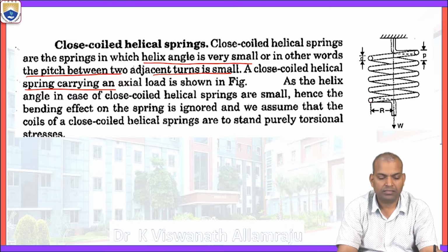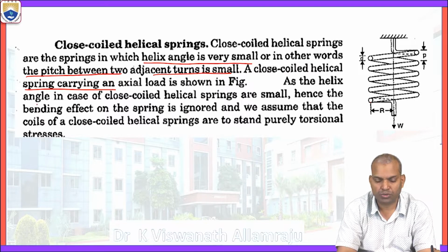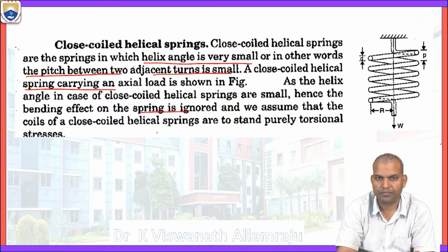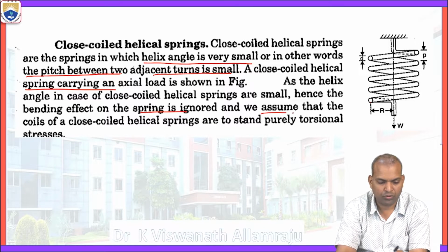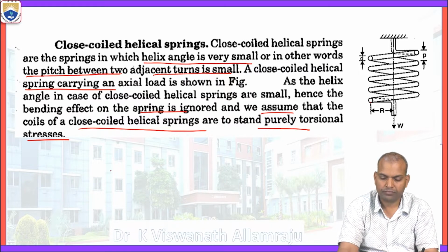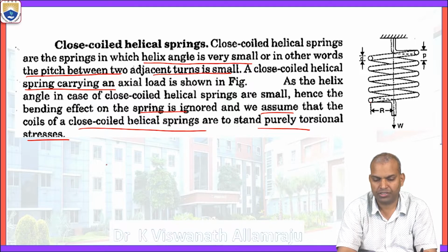As the helix angle is small, the bending effect on the spring is ignored, and we assume only purely torsional stresses.